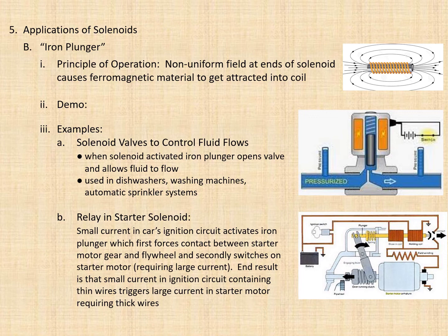So in a way, the starter relay or the starter solenoid functions very similar to a transistor in that it amplifies the power output. It can effectively switch a low current in the ignition system into a high current in the starter motor by using an electromagnetic solenoid rather than a semiconductor to perform the switching.